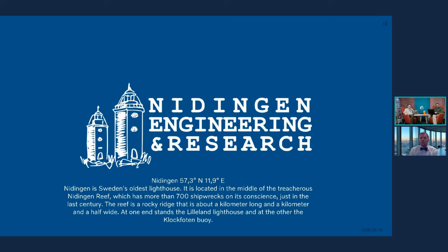Well, the difference is mainly the hydraulics. Since I don't have to worry about the hydraulics and the pressure losses, there's a lot of geometrical information I don't need when using the thermofluid, the yellow library. I don't need to know my pump curves, my fan curves, or my pressure drop in my radiator.